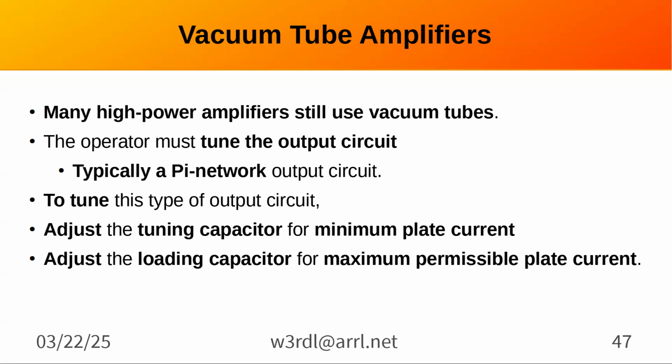So they compare the output, and some of the other manufacturers are doing a similar thing. You compare the output of the amplifier with a perfect wave, and then that difference you feed back and modify the input to correct for whatever, up, down, in order to get essentially a perfect sine wave out without third order harmonics. It kind of works apparently, but it's complicated, very, very processing intensive. Yeah. So it's an SDR linear.